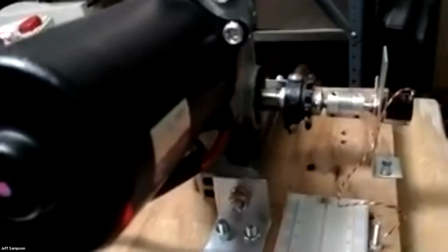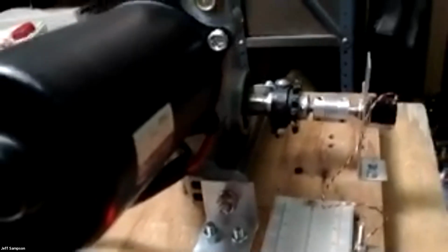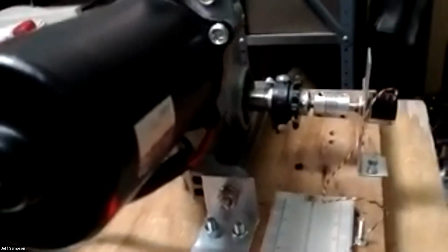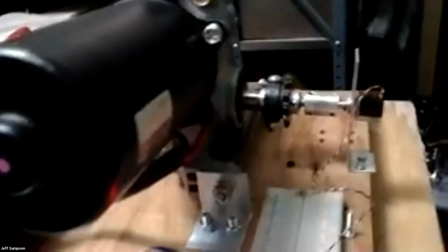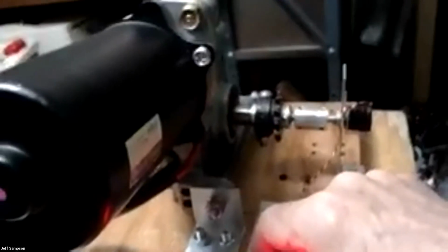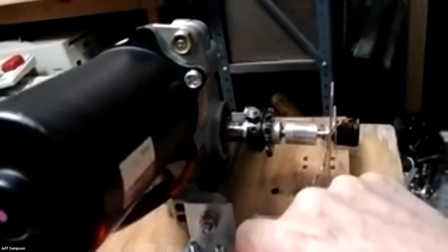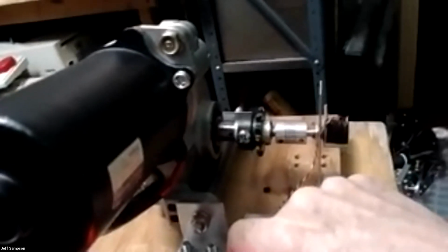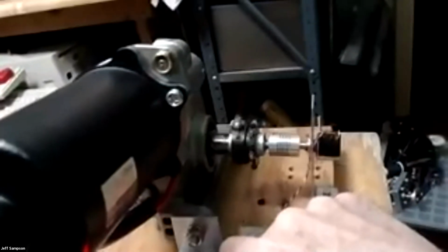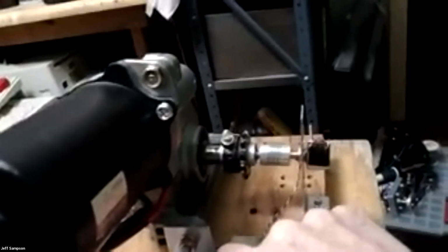So in one direction I picked a count of 256, and the other end is like 768 or something. So about 25% of the travel at each end is now invalid. If I move the pot back, the way that code's written, it'll start running again. Now I'm running, I get the other end here, and it shuts down at that end. I can't go beyond that because it says we're at the specified limit that I put.